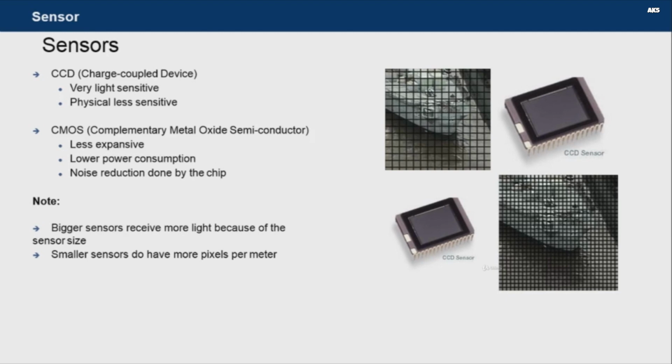In comparison with CCDs, CMOS sensors enable more integration possibilities and more functions, and have a faster readout, which is advantageous when high-resolution images are required. So megapixel CMOS sensors are more widely available and are less expensive than megapixel CCD sensors.